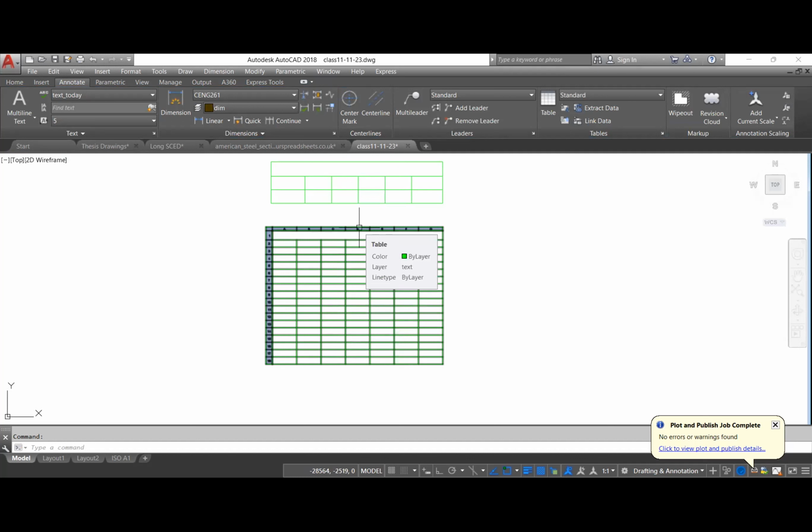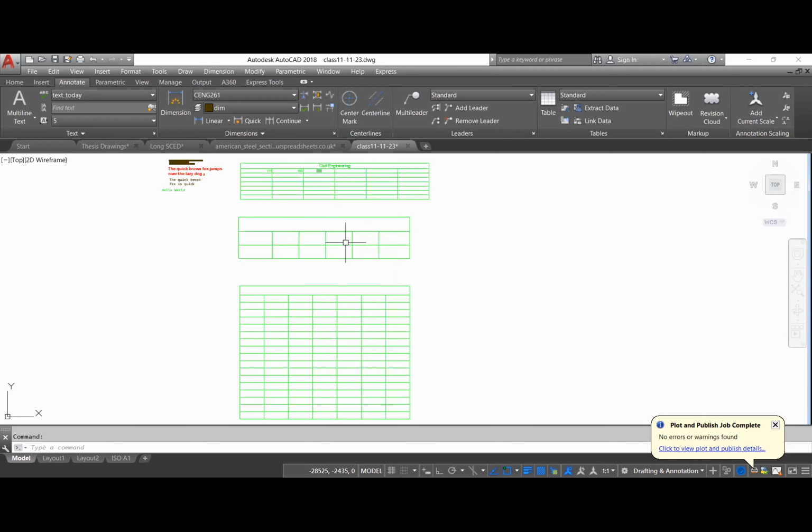Yeah. The only time you would use tables is if you are doing a bending schedule, right? We'll look at what that is hopefully from next week. It's data which gives information, especially with the rebars, how many rebars you are using, the size of rebar, and some other information that is critical to us being able to construct from your drawing. So I think this should be for the table, and then the text.